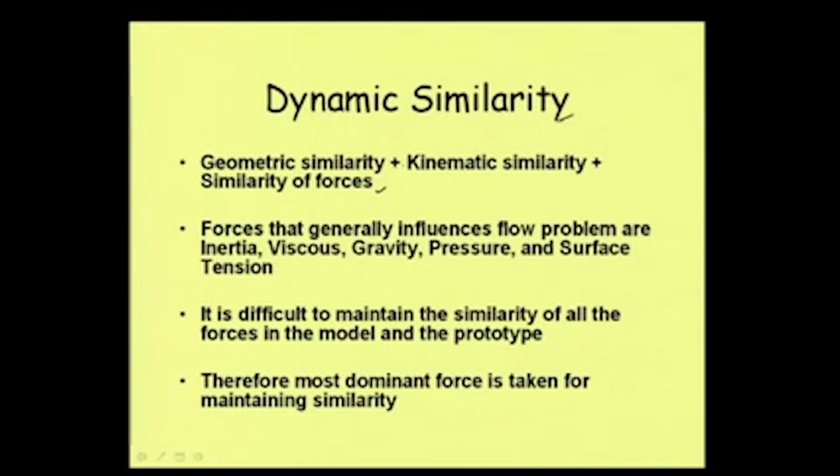Well, now this is very critical, because maintaining similarity of forces in the model and prototype, now we need to think about what force, because in a fluid flow problem there are so many forces that can influence the flow. Generally, the forces that influence a flow problem are inertia, then viscous force, then gravity, then pressure and surface tension. Elastic force will also be dominating if it is a pipe flow case. In open channel flow, of course, elasticity may not be that significant. Elasticity force will come when we consider the fluid to be compressible.